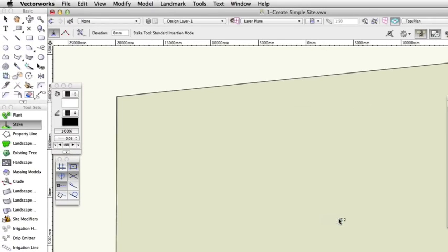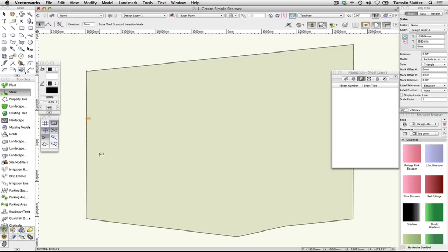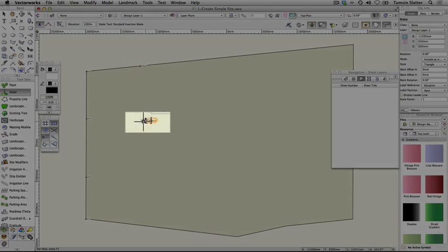On the toolbar, change Elevation to 0 and press Enter. On the left edge of the polyline, click at the corners and 2 points in between to create 4 stakes that represent the elevation of 0. On the toolbar, change elevation to 1000 mm. Roughly 1/4 along the length of the shape, place a vertical line of 4 stakes. Notice the new elevation is displayed by the stakes marker.